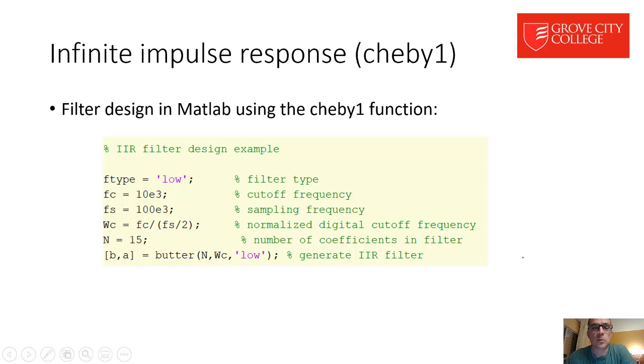All right, there's one other IIR filter technique that I think is worth you knowing because it behaves a little bit differently than the Butterworth. Depending on what is important to you in any given design, you might want to use one or you might want to use the other, and that's the Chebyshev function.